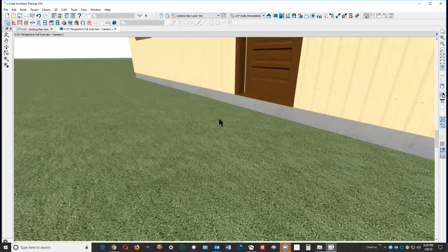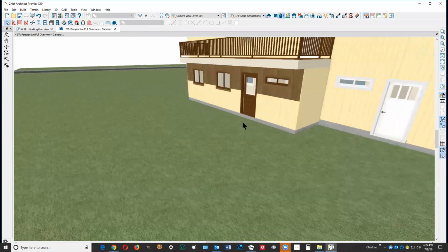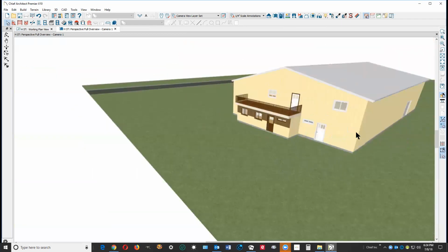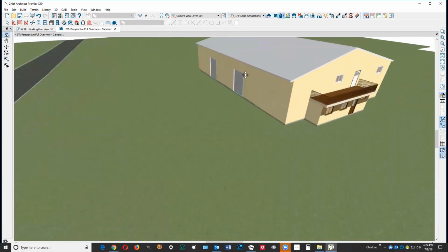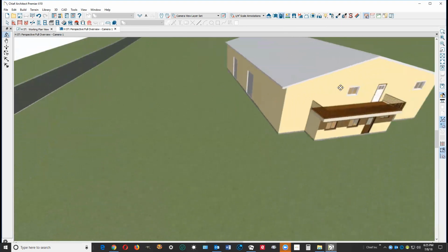And you put a landing out here. I can't think of the word I want. You're required to have a landing here and here. And then the garage doors are not required to have a landing. But the interior, it's assumed that the interior floor in the storage areas where you just want to drive in are at grade, and their floors are slanted towards the doors so that water doesn't run into the space.